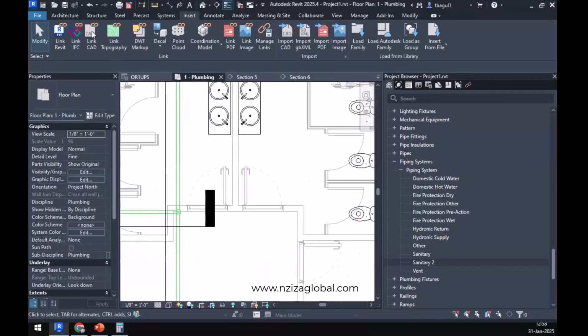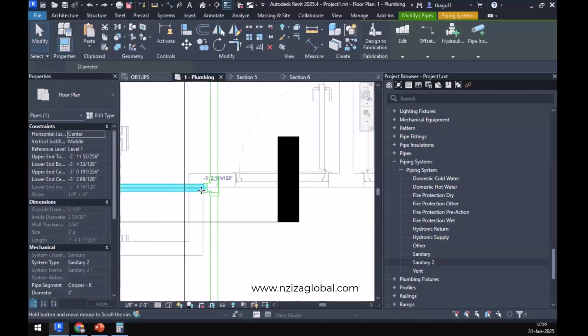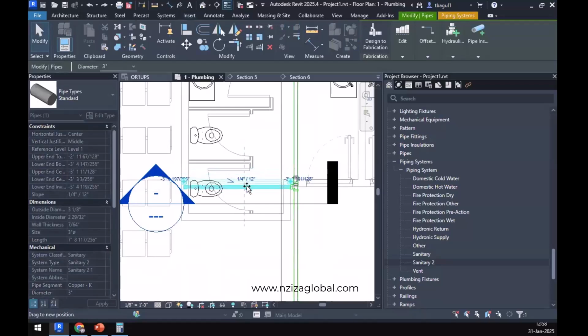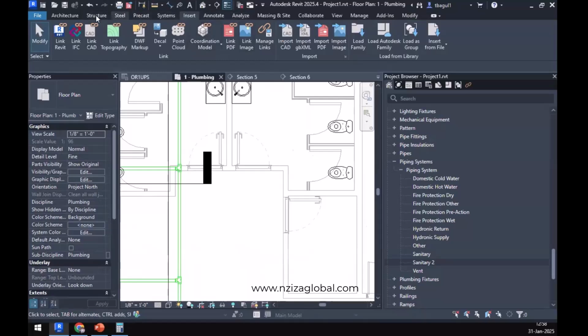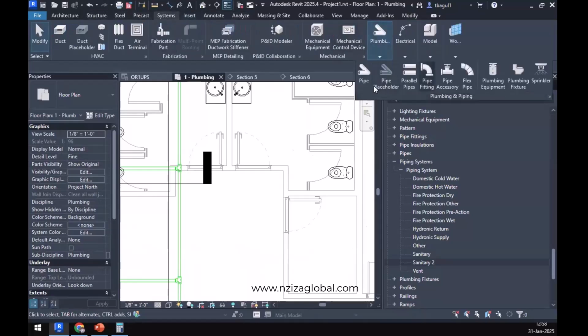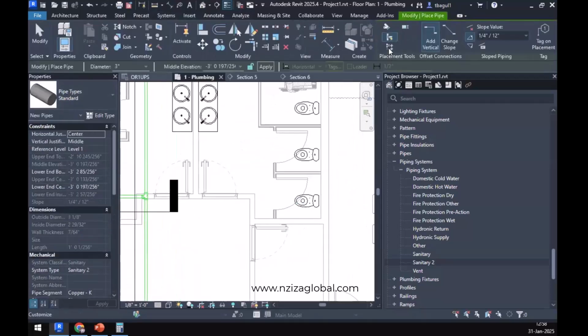All right. This is something inherent to Autodesk that will be hopefully resolved soon. But for avoiding that kind of issues, what I suggest you doing is have an offset between your connections so that you don't have to use a double Y joint. Okay. So if you have an offset for this particular pipe over here, then you can have another pipe that you can draw at a 3-inch with an inherent elevation sloping up from this point over.